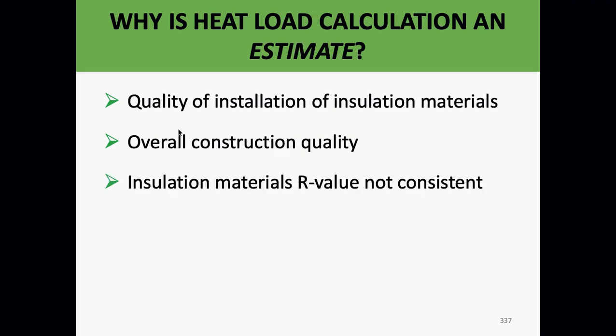So we also have insulation materials. R values are not consistent. What did I say happens to insulation as it gets crushed? What happens to the R value? As I crush insulation, as I compact it, what happens to the R values? Goes up. R value drops. U value goes up. Yeah, R value drops. It's going to be less insulation. The heat will flow through it more easily.